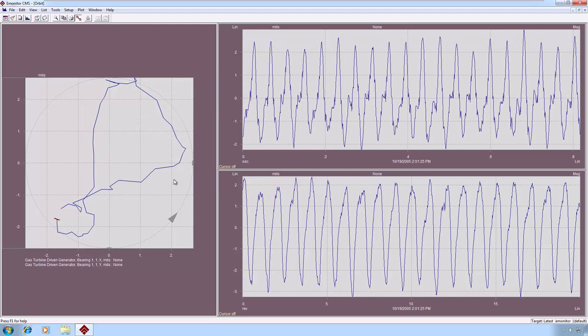This one is giving us sort of the characteristic figure 8 shape that is representative of a phase change. The direction of rotation is indicated by the arrow, and there's a little gray pad on the top and bottom which are indicating the specified sensor orientation, and those values are provided in the location pane. And you must fill in those sensor orientation values or you will not get the expected result in the orbit plot.